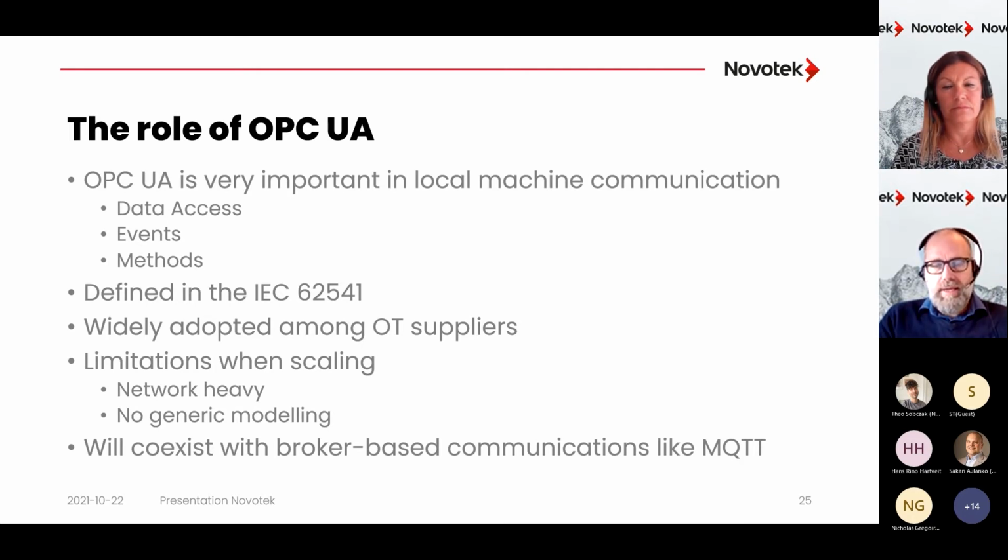It is focused on the more micro level than the macro level. Of course, you can build very advanced modeling in OPC also. And you have new technology with OPC UA called PubSub that can actually run over MQTT, but it's not that adopted as of today.